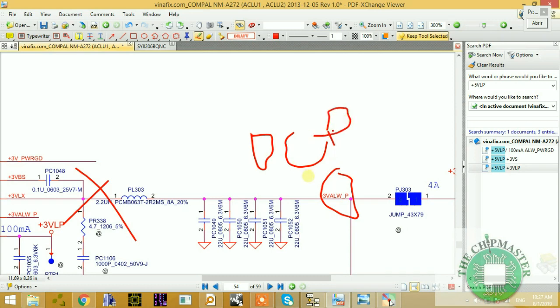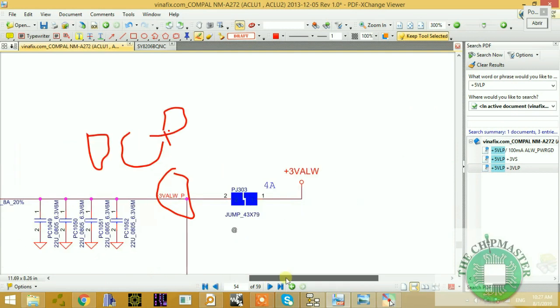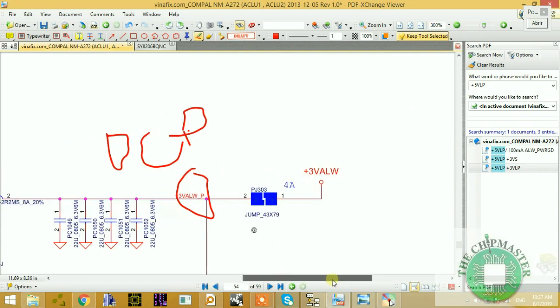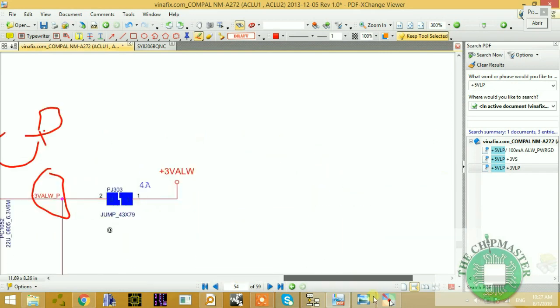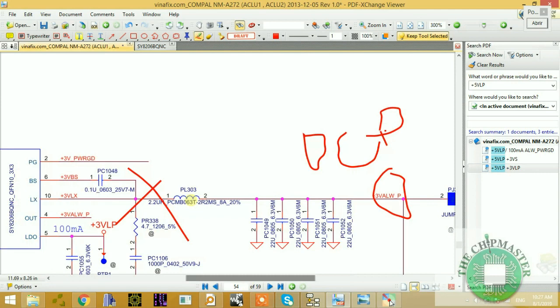When I'm going to show you the data sheet in the next segment, and some of the functions of these pins, for you to understand clearly, right? So if there's any overcurrent or any short circuit on this path, then it won't output any voltages because you have an overcurrent protection. So there's a short on this coil, so it will cut off the output voltage, right?